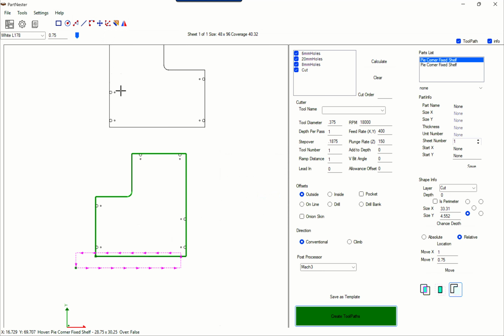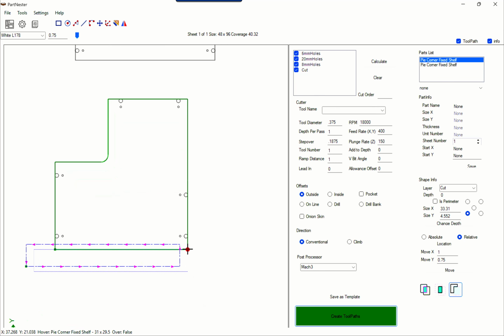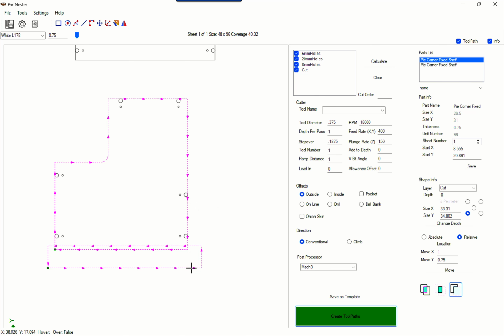I first have to select the part, then click move. And those values are still here, so I don't have to hit move. I could just type the arrow up and then move it to the right, and it bumps that shape by the distance that I have set. Anytime I click the right arrow, it is going to move 1 inch to the right. Anytime I click the down arrow, it is going to move 3/4 down, or the up arrow, it will move 3/4 up. So now selecting both of those shapes and creating a union again and going in and modifying the depth.